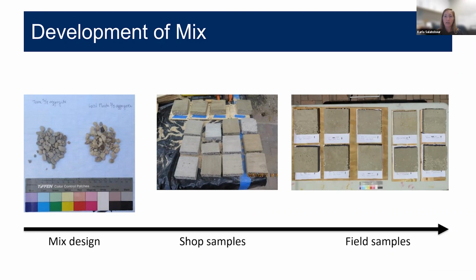And that's because we often don't have the same materials available for construction. So for example, stone or aggregates, sometimes those original quarries are no longer producing. And so we need to use a different material. For Portland cement, the cement we use now is much finer and of different chemistry than historic cements. Also, would we even want to use historic cement using ancient mixing and placing techniques? Likely no. Our technology today allows us to optimize our mix design and provide greater durability.